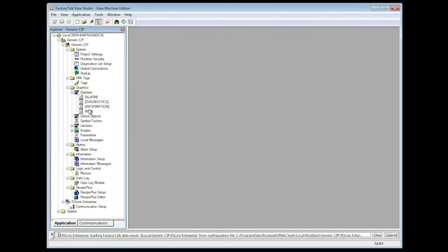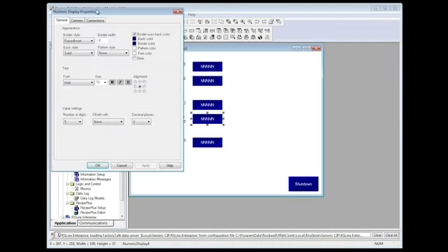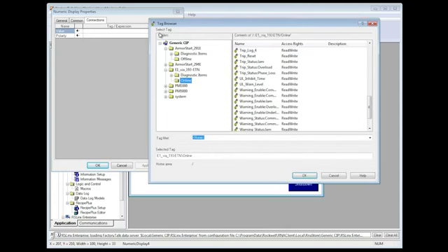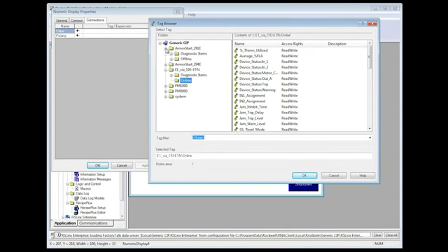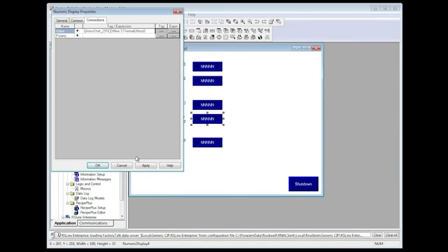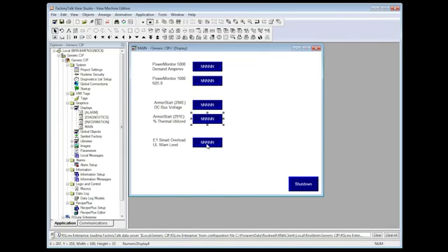To use tags from the devices on the display, simply use the tag browser built into View Studio, just like you would for a controller. You find the shortcut, open the offline folder, and browse for the tag and then add it to your control.